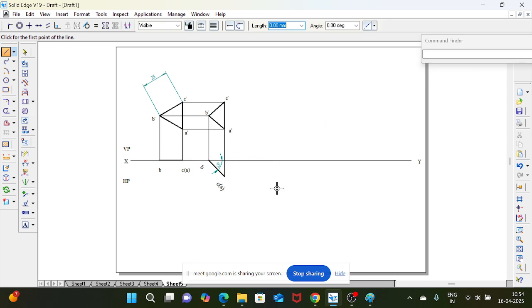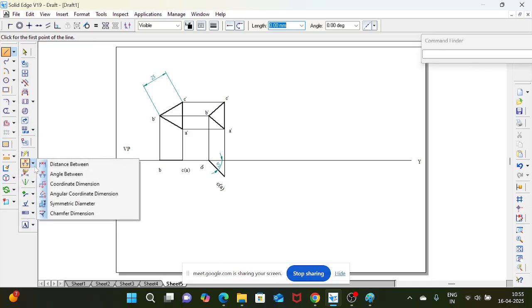Now you can see, yesterday I shared one image where I have given the steps to be followed to solve the problem. First step, identify the type of plane. Second step, identify edge or corner resting. Identify HP or VP resting. Then identify the primary reference plane. Give the inclination to the primary reference plane. Now identify the reference for secondary reference plane inclination. Now the reference will be the median.